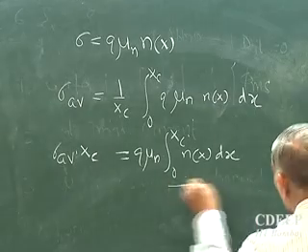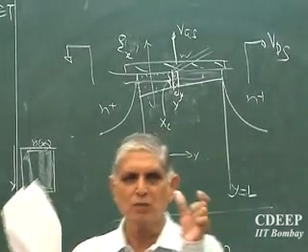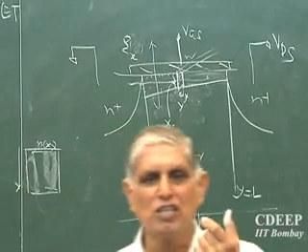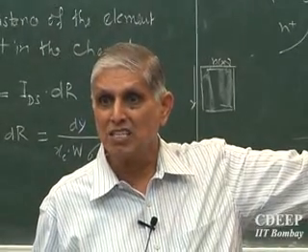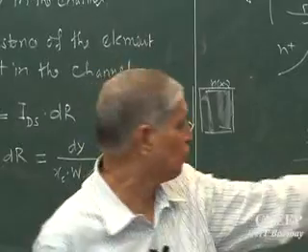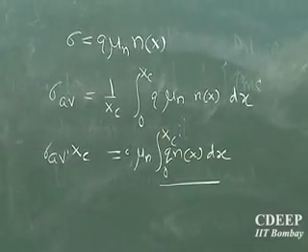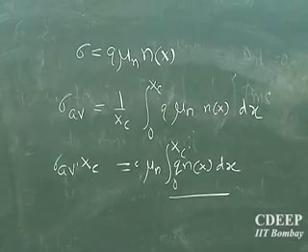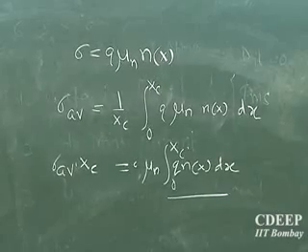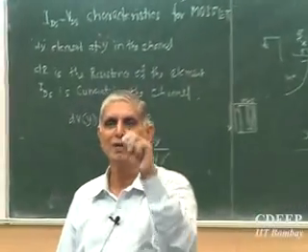now what is this? Can you tell me? What is this nx dx that I am looking for in this part? What is this part in the whole channel? This is the inversion charge. Please remember, nx dx means how much? Density. Nx dx is density now, charge, and if I put q inside this, this is nothing but inversion charge at y. Is that correct? This is inversion charge density at y. Is that clear, Pawan? Nx dx into q, if I integrate over this, per cc into distance is per centimeter square, q if I multiply it to charge.